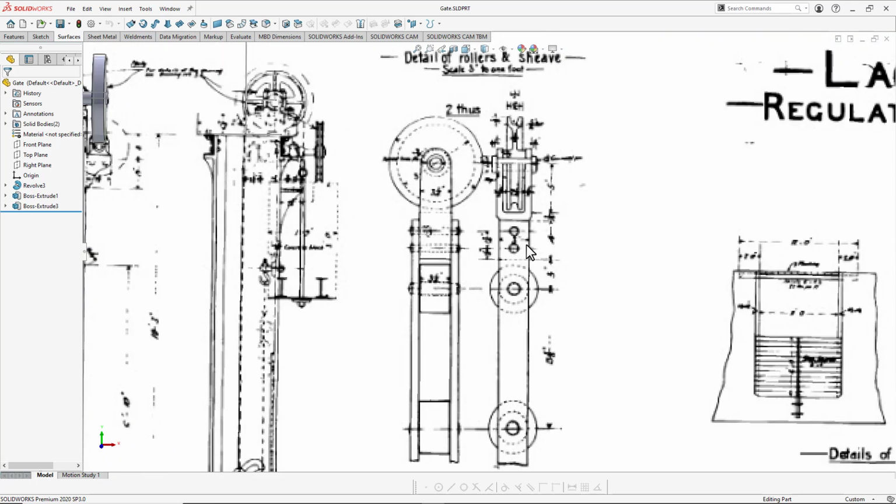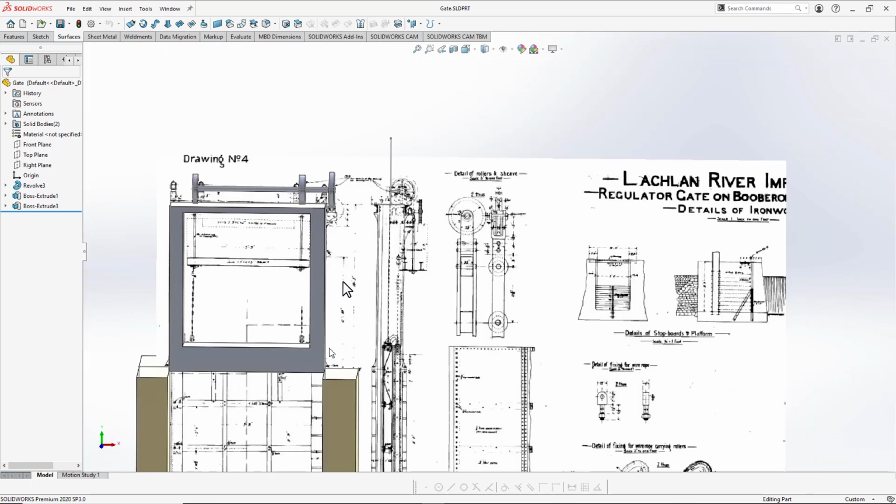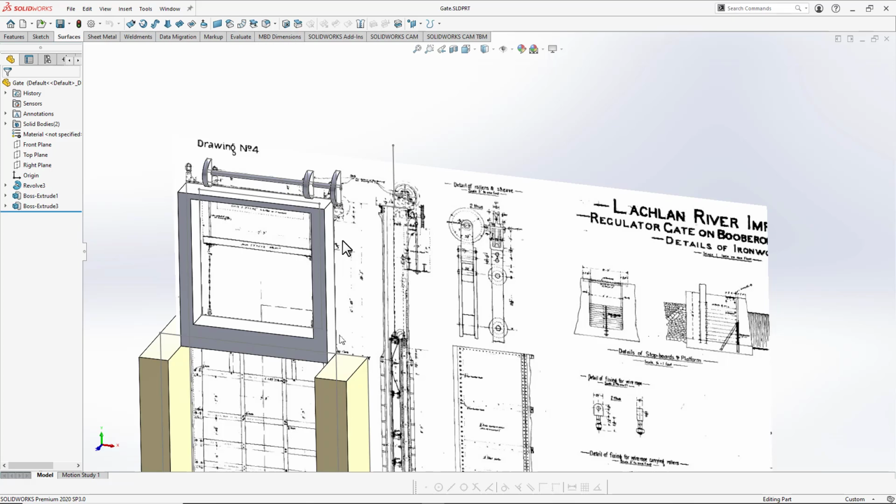They're very bad quality. So I decided to import the picture into SOLIDWORKS, use those dimensions that I can read as reference, scale up the picture, and then create the 3D model accordingly. This gives me a very rough estimate of the sizes. It is not very accurate, but it is accurate enough, and in most cases you can rely on the dimensions that you get off this method. Depends on the project though, and also how accurate you are while following the procedure.